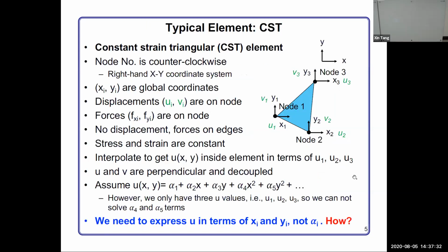Okay. Now, today let's talk about a fundamental finite element type, which is called a CST. CST stands for constant strain triangle. You can also call it a constant stress triangle. It's also CST, and as you will see, that definition is also correct. Now, here is one example of one CST element.